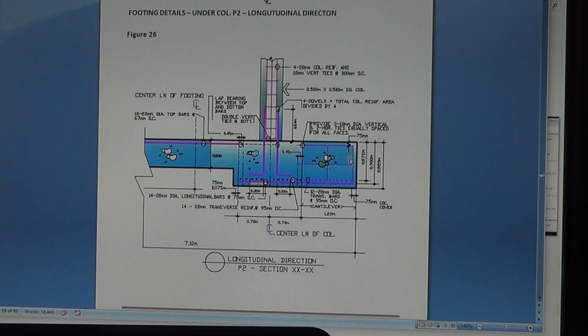This is the stirrups, the vertical bar, and if it's 2 to 3 feet deep, this is about 3 feet, it's 0.9. So I provided stirrups right there, and then one horizontal web reinforcement. This is a web reinforcement right here, the vertical, 3 of them there. This is the most critical part of the foundation because this is open here, there's no column here. It's going to shear off right here. Never mind here, it's not going to shear there, there's a lot of concrete here.